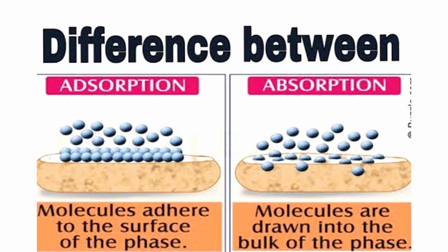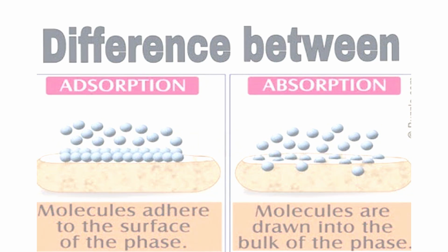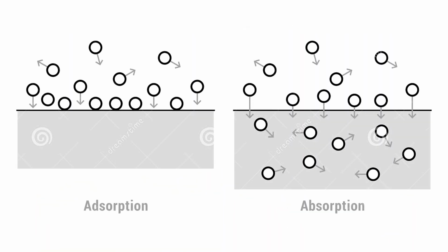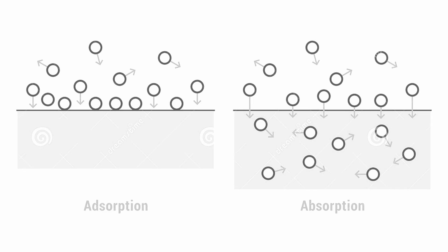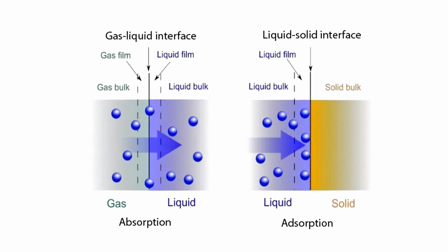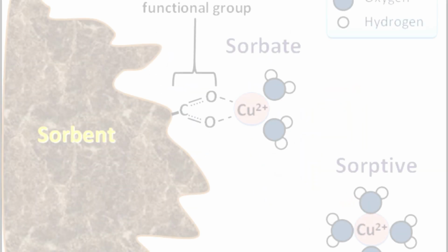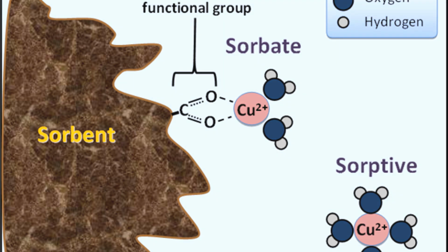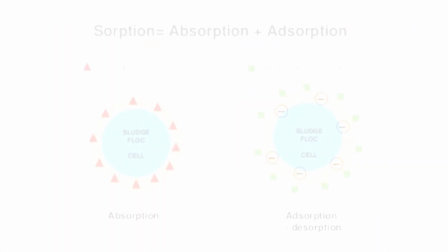There is academic interest in whether the ion exchange process is an absorption or an adsorption process. Adsorption is a process that occurs at an interface or surface involving the interaction of ions. Absorption involves the incorporation of a substance in one state that attracts another in another state, such as solids attracting liquids throughout their entire structure.